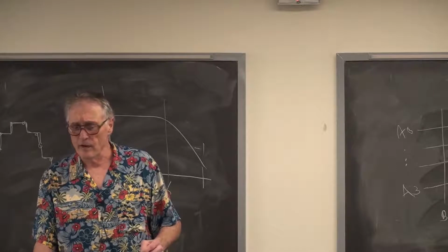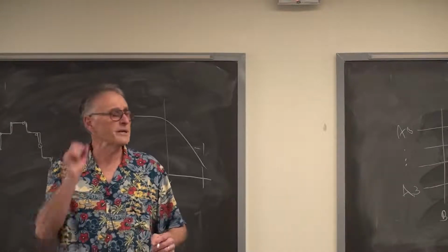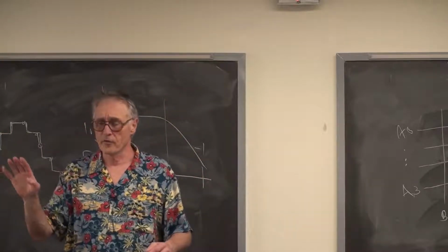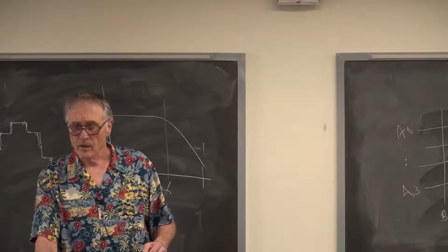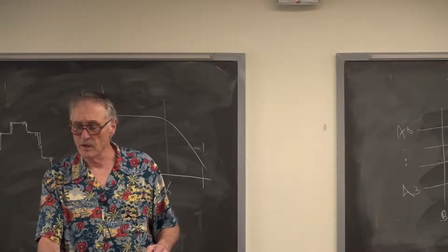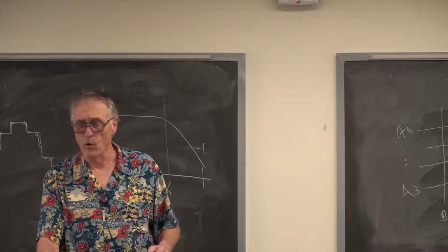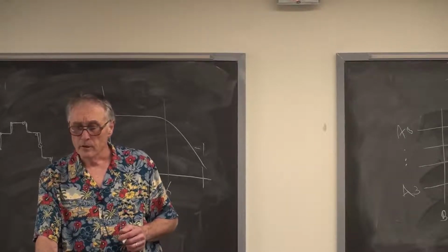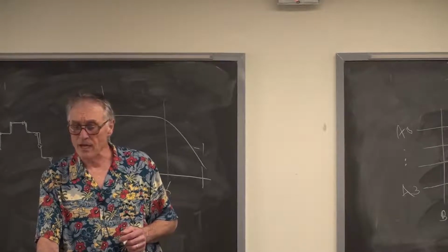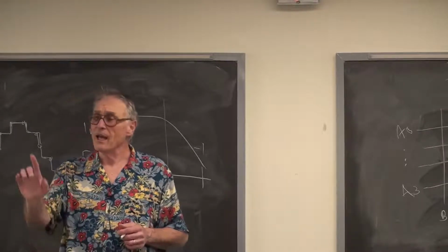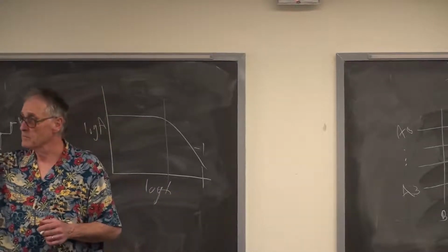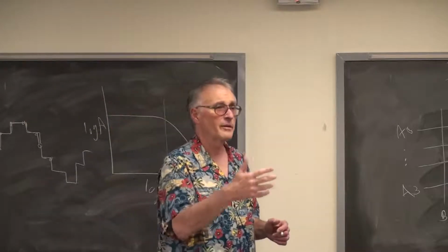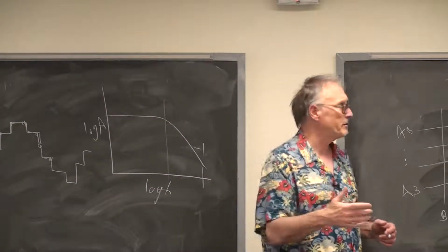I'm going to ask you to have all time intervals and burst duration accuracy be plus or minus 1 millisecond. That's so you can use the tick timer in protothreads for timing events. Each sine wave burst has to be amplitude modulated from 0 to full amplitude in 4 or 5 milliseconds. There can be separate control buttons for play, stop, and test, and those do not have to be on the keypad. It is possible to make a shift key on the keypad so you can double the number of functions. It is just really annoying to do that.